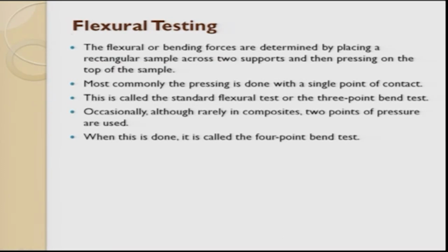The next thing is flexural testing. I cannot make very long samples because my products are very small. So generally in thermoplastics we try to do flexural testing. Flexural testing, or a bending force test, is determined by placing a rectangular sample. We keep two supports here and apply a load here. Okay, two supports and then press a load.